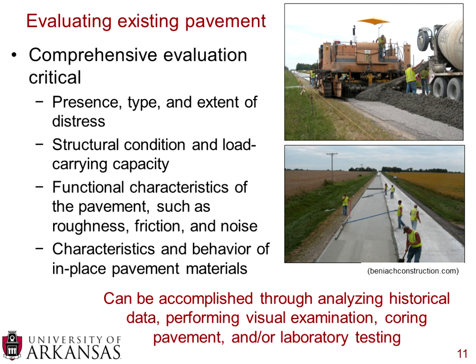You want to know what the structural condition is and also what the load carrying capacity is. So this is where a falling weight deflectometer, an FWD, would come in handy to know what kind of pavement layer is already in place and what you are getting out of that, and also knowing what you need in addition in order to have your road serviceable.